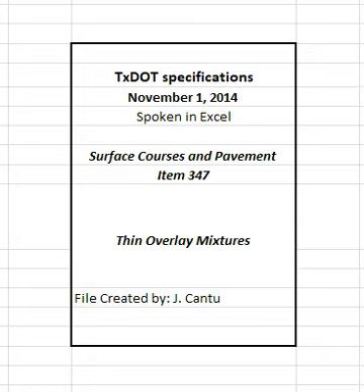Additives that facilitate mixing, compaction, or improve the quality of the mixture are allowed when approved. Provide the engineer with documentation such as the bill of lading showing the quantity of additives used in the project unless otherwise directed. 2.6.1 Lime and liquid anti-stripping agent. When lime or a liquid anti-stripping agent is used, add in accordance with Item 301, Asphalt Anti-Stripping Agents.